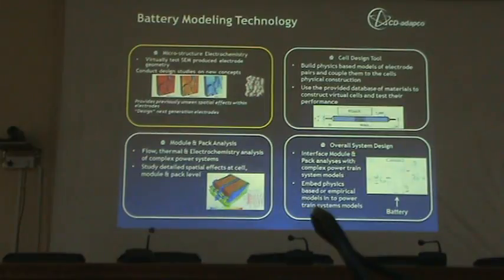Typically in CFD, the length scales which we look at, let me tell you, my client is Shell, so we look at pipelines of 100 meters and we try to analyze annular flows at such length scales. So typically CFD is generally for higher length scale problems. When you move to this kind of length scale, you have to refine your mesh. Let me put it this way: the problem will be computationally very expensive. You need much higher computing power or cores, and you need much more time to run such simulations.